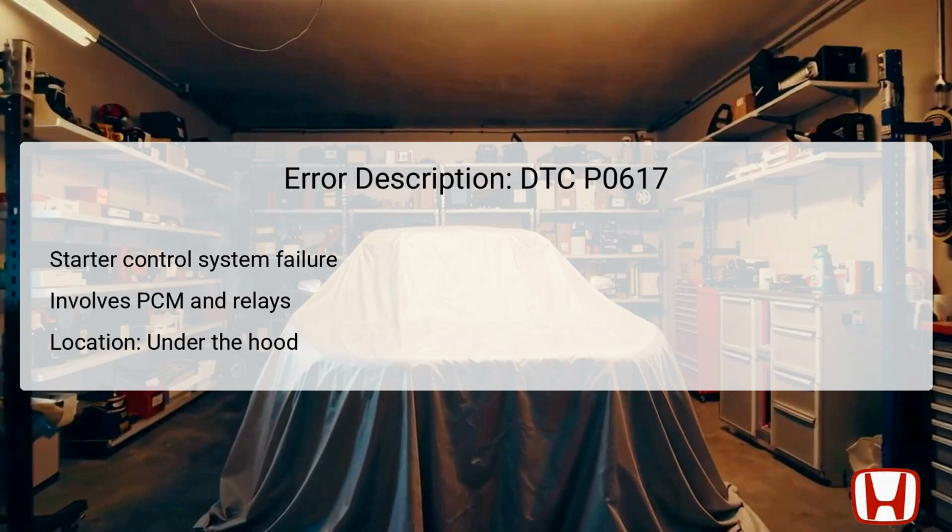If the vehicle's shift lever is not in P, park, or N, neutral position for CVT models, or if the clutch pedal is not engaged in MT models, the PCM cuts the power supply to the starter relays. The relays then monitor the voltage between them for any abnormalities. If there's an anomaly, such as a high voltage reading, the PCM records this as a fault, triggering the DTC P0617. Understanding this error code is crucial for diagnosing and rectifying starting issues effectively.